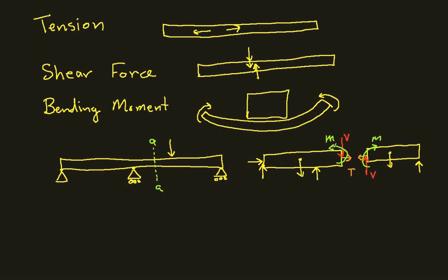And then M is drawn as if you think of this beam up here, or we'll draw some scary teeth in it, as a smile. If I'm looking at the right end of a beam, so if I'm over here, then I draw the bending moment up around it like this, so it looks like cheeks on a smile, basically, and the opposite direction if I'm on the left end.